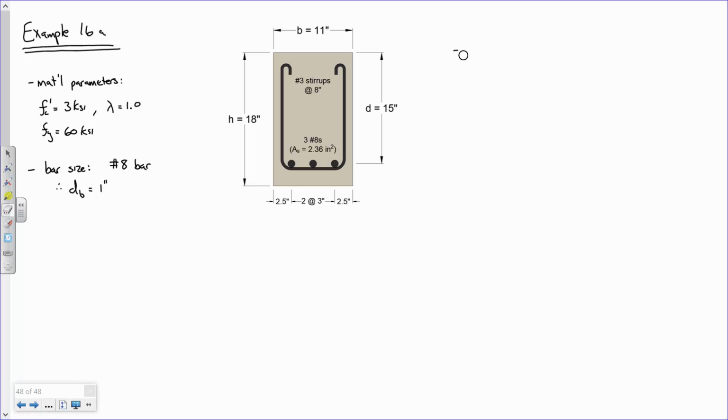All right. So there's 3 of them that we need to consider for this model. Let's start off with psi t. Now that's our top bar factor. What's that going to be for this problem? It's 1. Why? Because these are bottom bars.